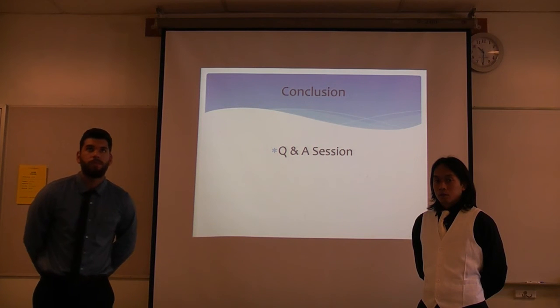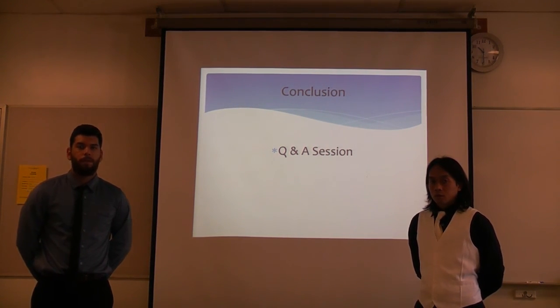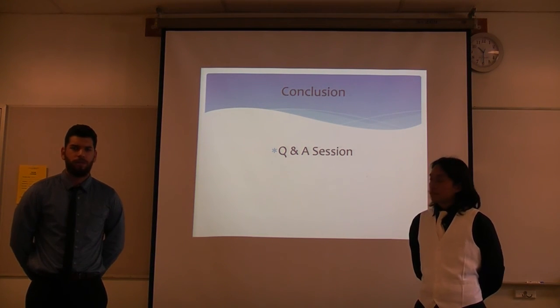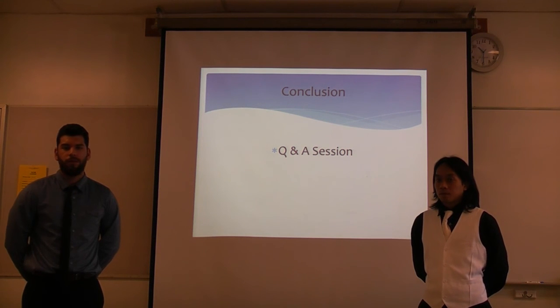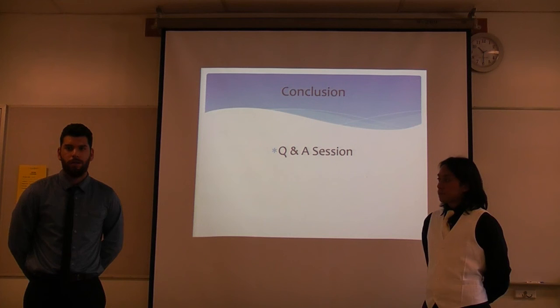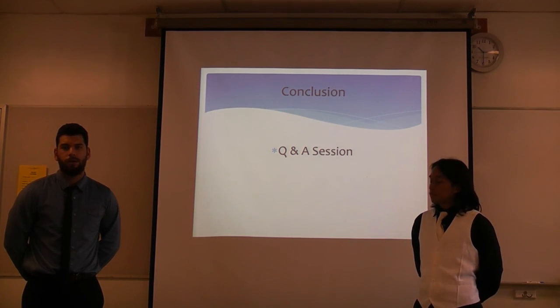What was the pre-increment, pre-decrement, or post-decrement? You said you had that set up for the loads and stores? Yeah. It would operate the same way as a load, except the IDP would be implemented, and it would be used to take the source operand and either increment it by one and restore it back into the register file.